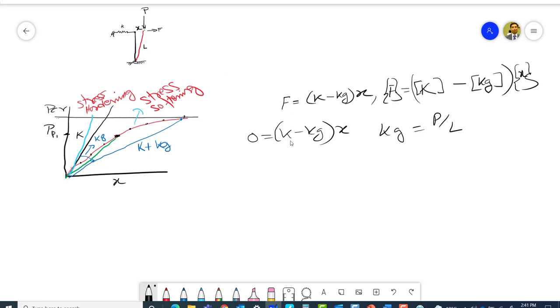So you can understand that if my resultant stiffness is zero, that means I need the slightest nudge applied at the structural tip to destabilize the structure, or to impart a collapse. This is the point where the buckling arises. So buckling means you need a zero amount of load, but actually it's not zero; the slightest amount of lateral push or the slightest amount of a second order moment would be there, and that would be enough to destabilize the structure, because in a real life scenario there would be the slightest lateral sway or some eccentric moment or some out of plumbness. That would be enough to destabilize the structure, and that is where the buckling would arise.